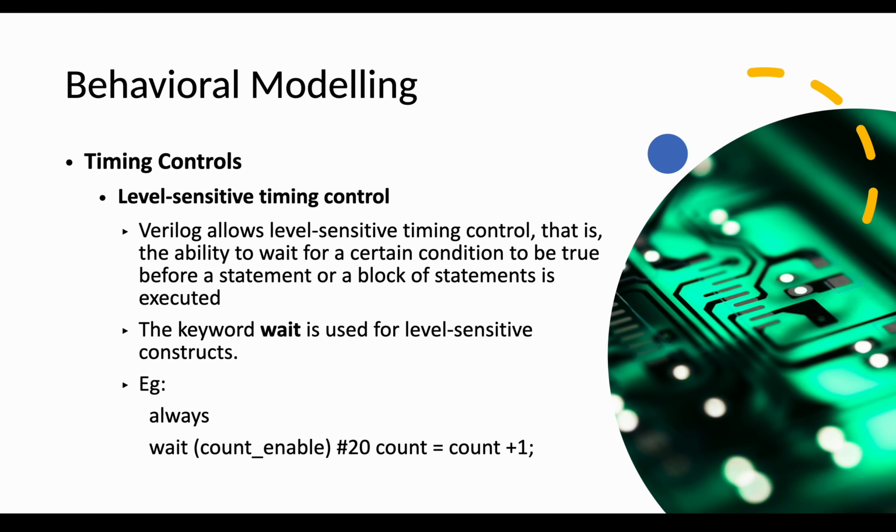Then level sensitive timing control. Verilog allows level sensitive timing control, that is, the ability to wait for a certain condition to be true before a statement or a block of statements is executed. The keyword wait is used for level sensitive constructs.